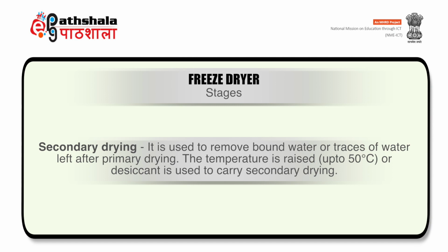It is used to remove bound water or traces of water left after primary drying. The temperature is raised up to 50 degrees Celsius, or desiccant is used to carry out secondary drying.